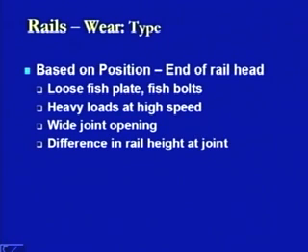Whereas, if a wheel is coming from a lower level section of the rail and tries to negotiate a higher level section jointed at a certain point, then some force will be transferred at the forward section which is at a higher level, and due to this force there will be a movement in the forward direction in the rail section because of the horizontal component of that force. So, these are the two things which can happen because of the difference in rail height at the joint.